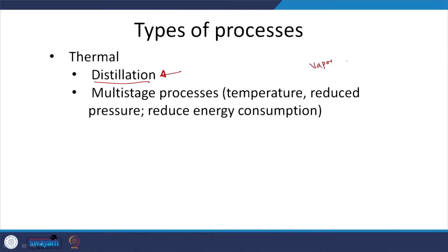So, the vapor can later be condensed and used for water. So, distillation, but the conventional way, it's too costly, too much energy. So, what do they try to do? To my understanding, they try to decrease the vapor pressure, so that even at relatively low temperatures, the water can be boiled. That is where I believe the efficiency of the system comes into place, but in general this is not widely used, at least for desalination. That is one aspect to keep in mind.